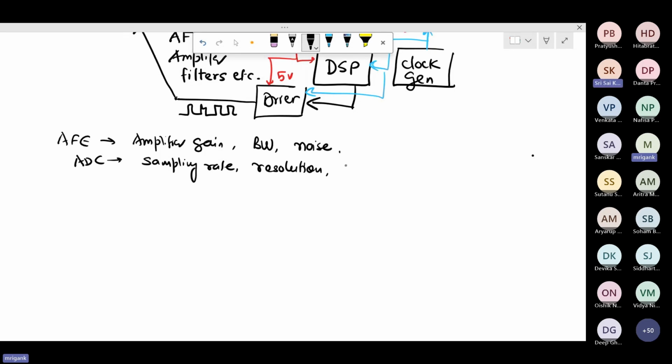There are some parameters related to non-linearity, because ideally we would like the ADC to be perfectly linear, but in the real world it is not. It has some imperfections. So this non-linearity is measured in terms of INL, DNL, etc. There are some other parameters related to distortion in the ADC. Dynamic parameters are there, SNDR, SFDR, but at least the basic things are these.